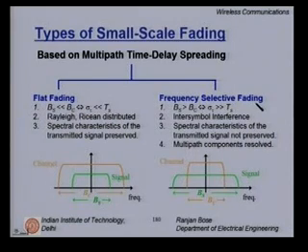Whereas, in the frequency selective situation, the bandwidth of the signal is larger than that of the coherence bandwidth. I do expect that my received signal will be distorted when I look at it from the frequency domain perspective. Question: in frequency flat fading, we don't expect the signal to be distorted, and therefore, what's the best way to restore the signal if it goes into a fade?